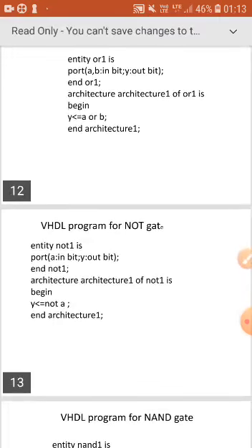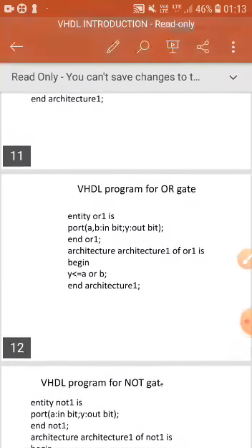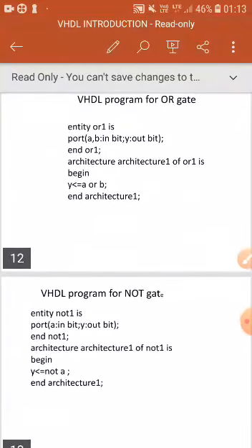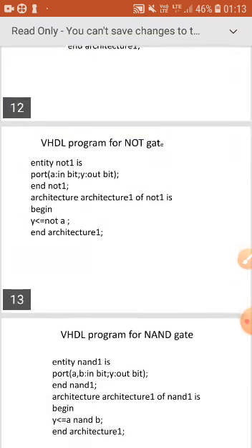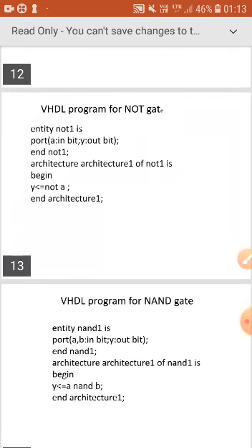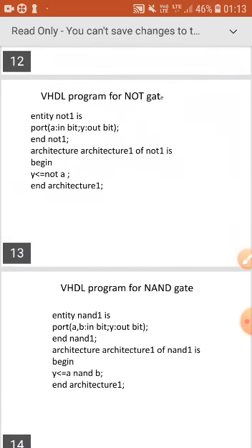Next, inside the architecture I am defining the logic. This is the VHDL program for the OR gate. So y is equal to A or B, so y less than or equal to A or B. Next we will see the VHDL program for the NOT gate.